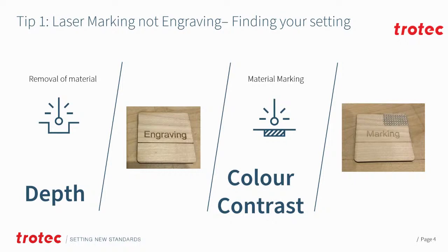So if we look at traditional engraving, so we're having a look at the actual engraving mark itself. What we traditionally try to do is go for quite a deep mark which creates a nice amount of contrast, and this is a great effect and is especially useful for things like your basic text. However, when we aim for this area and fire the laser here, we input a lot of energy in order to get this depth, and quite often that will result in an engraving mark that's quite a bit wider than where we're targeting the laser.